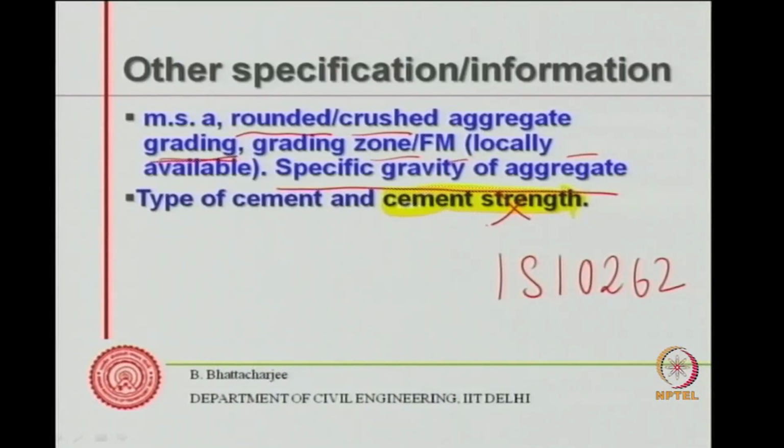Now, type of cement is important, particularly related to durability. Well, this information is important in the sense that from the point of view of minimum cement content, this has got some importance, not really much. But what would be important for us to know from our possibly past experience or from our record is the kind of strength to water cement ratio relationship for concrete. That becomes an important issue. Anyway, type of cement may be specified, because this is what you would be using. So if you have to do a trial casting, you have to use that particular type of cement. If I am using some admixtures, what is the kind of admixtures I am using? That information is important, and its compatibility with the cement and the other system, the overall system, that is also an important aspect.